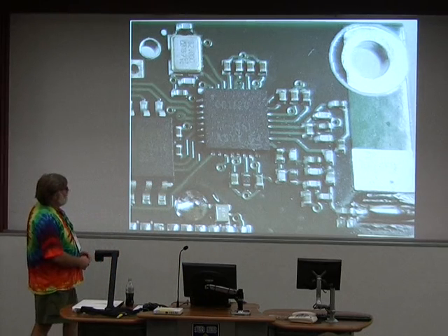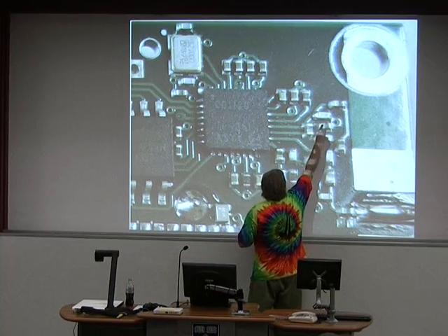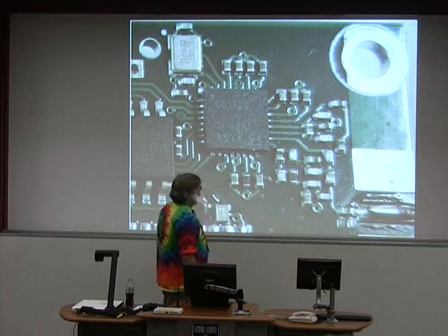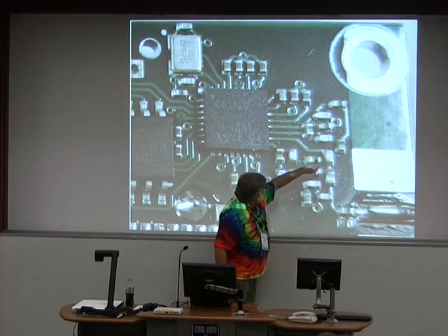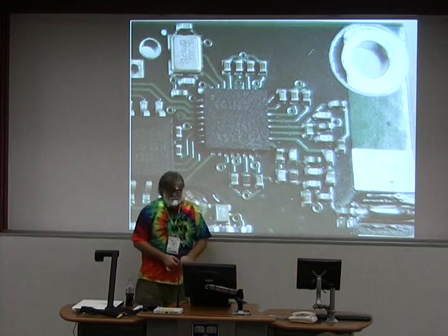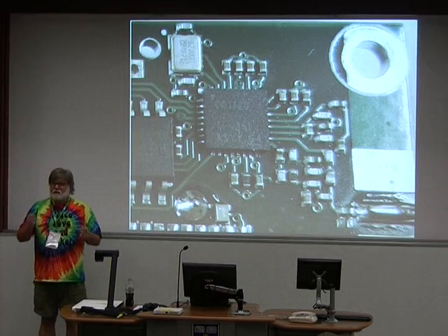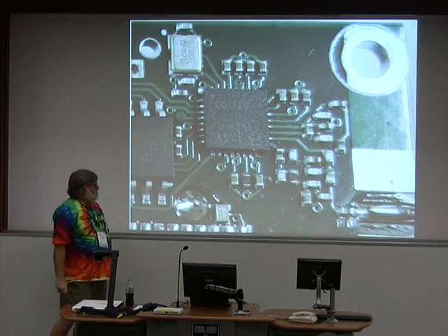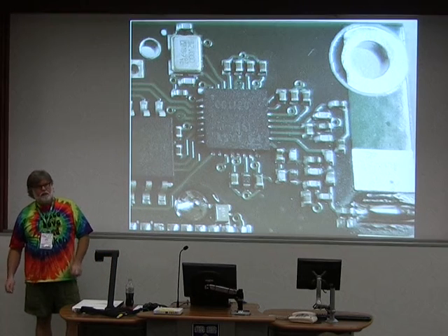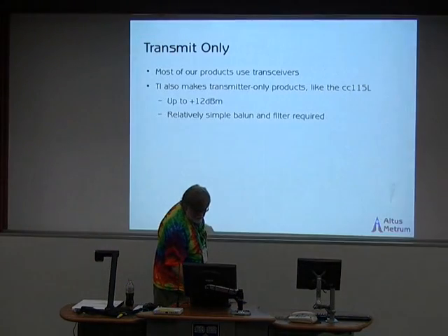But once again, you'll notice that here's another pair of inductors that are very carefully mounted orthogonally to each other. There's another pair there. It's interesting. Some of this ends up being almost art when you're sitting there in the CAD system trying to get these things right. It's unfortunately just time consuming and expensive enough running cycles that you don't try as many things as you'd really like.